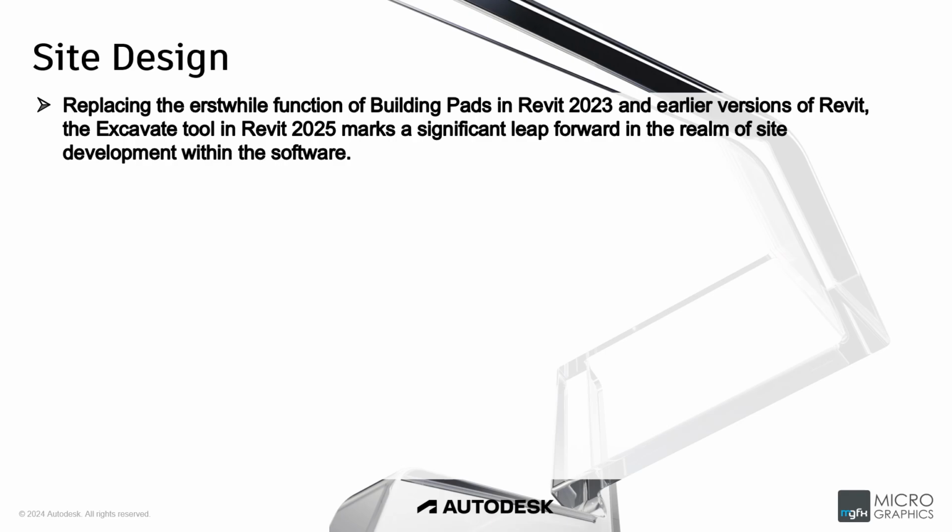At its core, the Excavate tool allows users to precisely sculpt topography and excavate volumes for topo solids using various cutting elements, such as floors, roofs, masses, or other topo solids themselves. Whether it's creating a sloping terrain for a residential project or carving out space for underground parking, the Excavate tool offers unparalleled flexibility and control.